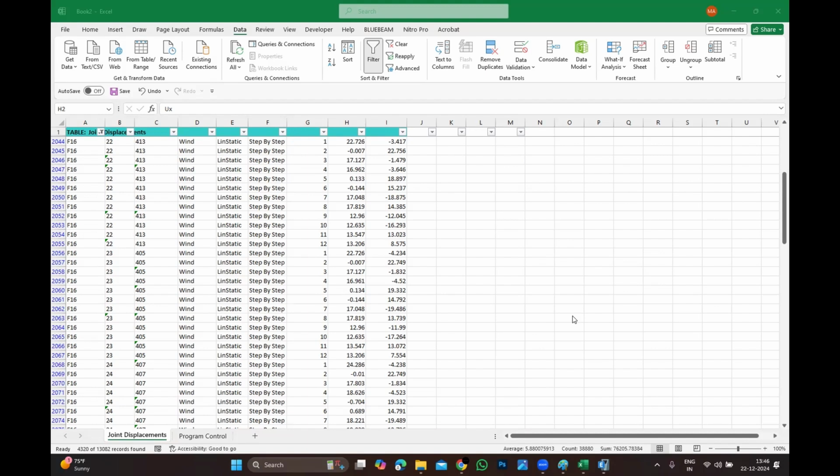Only the top roof. If you control that, and if you're putting a beam on the top roof, no one is going to have an objection. You can even put an inverted beam. If there is an objection, take this beam as an inverted beam, that's it. Then this beam can act as a parapet as well.